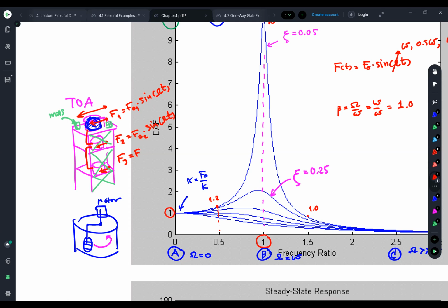Therefore, the total force, as your friend explained before, is minimized. We will cancel each other. The mixing force will cancel each other from mixing machine number 1 on the top floor and number 2 on the second floor. And that's why the vibration of the steel frame is very small after the program controls the mixing like that. Okay, thank you for sharing.